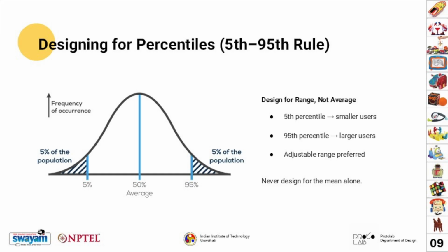Let me elaborate. For reach, grip size and access, design for the 5th percentile ensures the smallest children in your target age group can comfortably hold, press, reach out, or operate the toy. Example, button spacing, handle diameter, trigger force. If the smallest child can use it, most larger children can too.